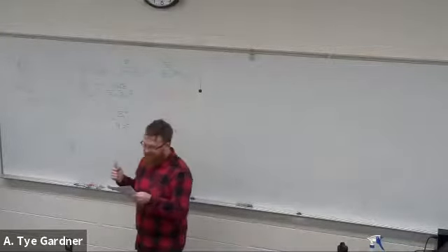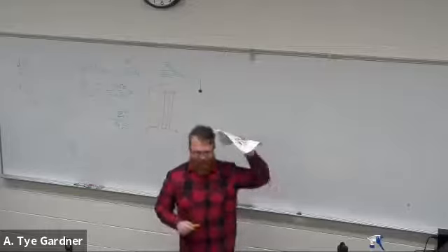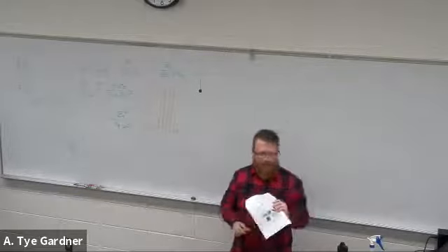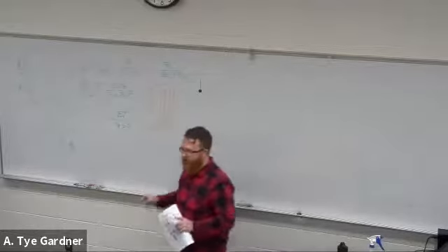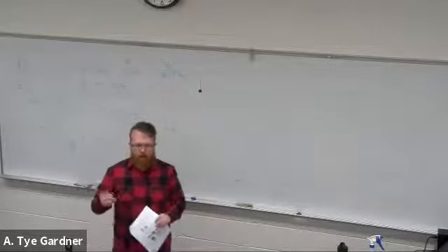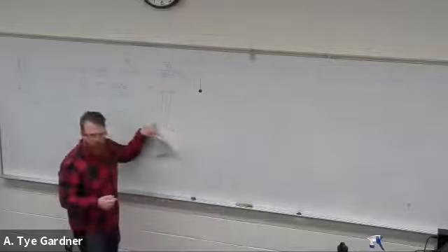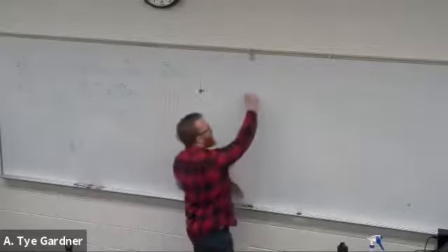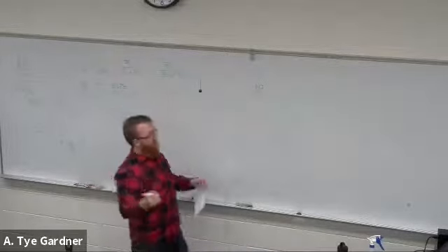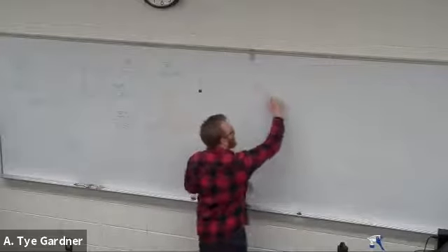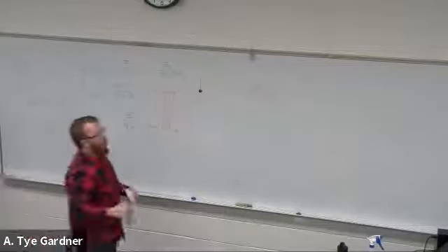It's brutal. So what I'm going to do instead is the smart way, which is what Jeremy was starting to do in the lab last week, which is just look at what it should be. So what should the sensitivity of the strain gauge be? What is it really measuring? Well, we know that the output is going to be a delta R, right? That we know is measuring. So that goes in the top. And we can quickly make the argument that it should be normalized to R naught, the initial resistance under zero strain. So that's our output.